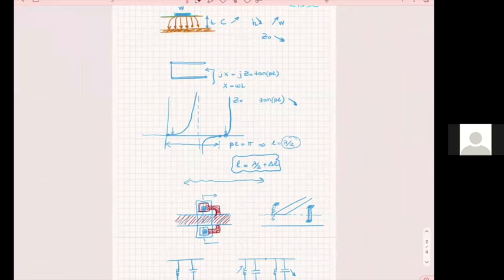Keep this in mind for all of your designs, whether you have to do them with microstrip as we do, or in real life using another line. If you come out from your designs with unreasonable values of length or characteristic impedance, then you know that using transmission lines to realize them is not possible. And then you go and you look at other options.